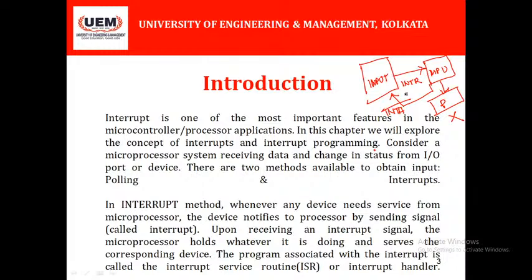The program associated with the interrupt is called the interrupt service routine or interrupt handler. Whenever the microprocessor MPU is handling this interrupt, it is using a special subroutine or special program known as ISR. Each ISR has a unique address known as the vector address.